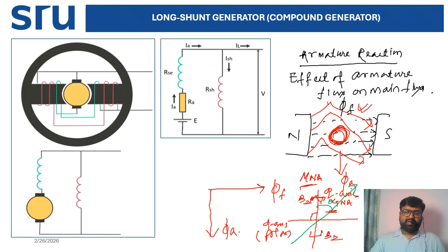Even if we turn off the supply voltage, the generator still has some energy, meaning the generator voltage will not drop to zero immediately. Then there is a huge loss, and as it opposes the field flux, there will definitely be a reduction of field flux.